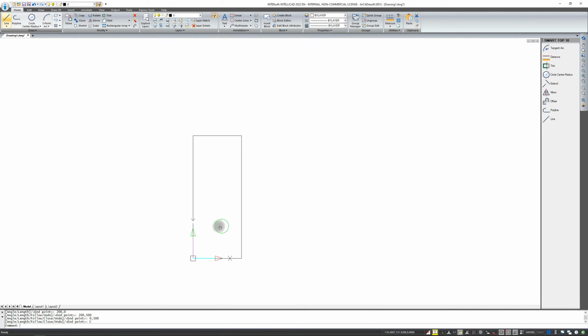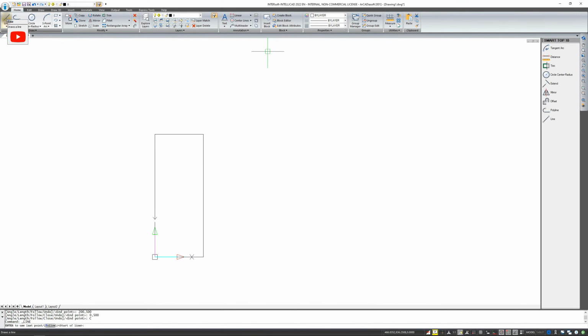If I only type coordinates, of course, after approval, I still have to exit the option with the right mouse button, enter or escape. If you do not turn off the dynamic entry window when you start drawing from any point, you have to remember that it is relative drawing. And if I draw exactly the same rectangle, before entering the value I have to enter the at sign, and then enter exactly the same first values that were in the introduction of absolute coordinates. Remembering that at this moment, exactly at the place I clicked, the program introduces a temporary point 0,0 of your coordinate system.